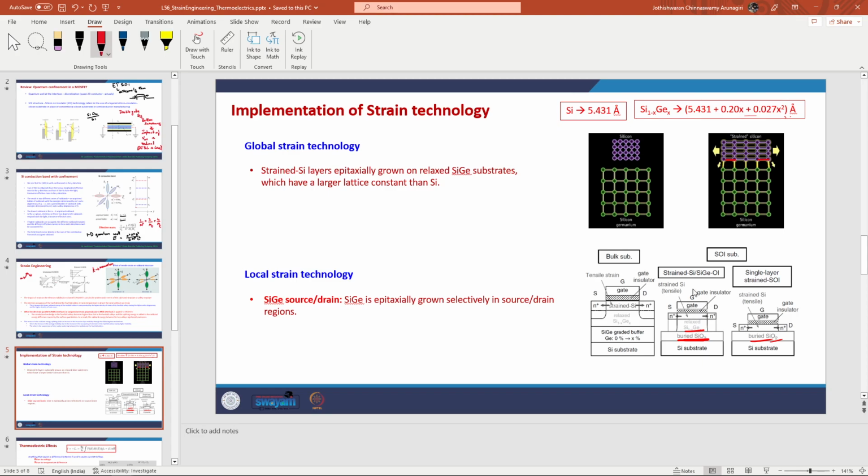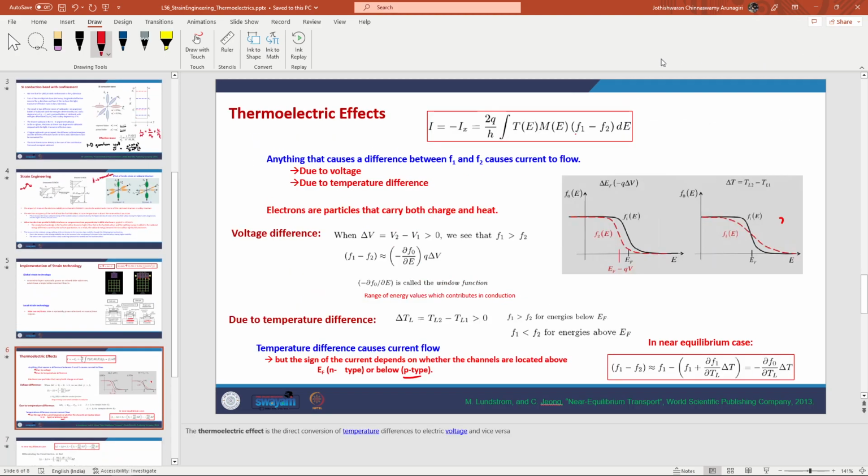So, in this, what we essentially do, like that is essentially what I described before, we change the geometry of the gate. Like we essentially have an enveloping gate, or we have double gates, or some other kind of configuration like silicon on insulator configuration where the strain is applied locally by the gate terminal. So essentially from point to point on the device, we implement these strained regions, and therefore in those strained regions we will have the enhanced electron mobility and other behaviors.